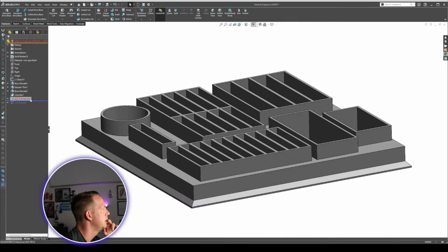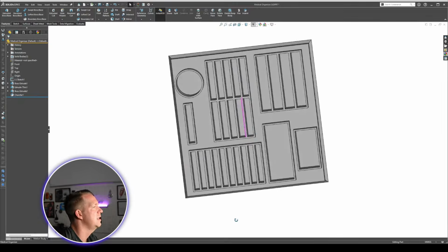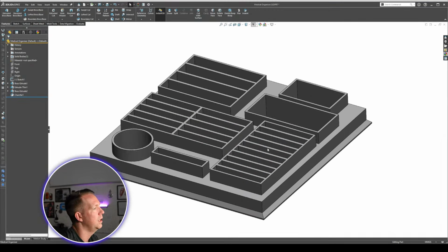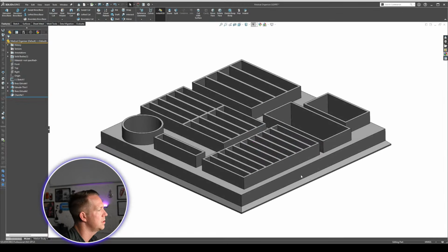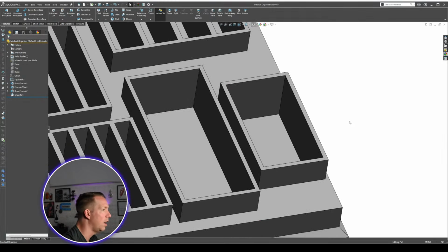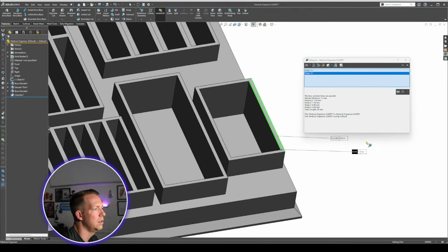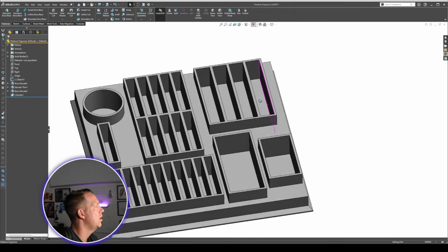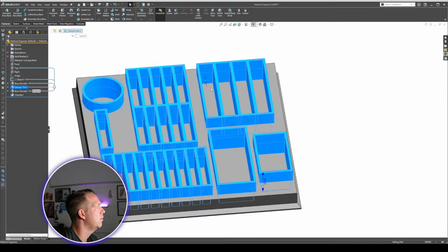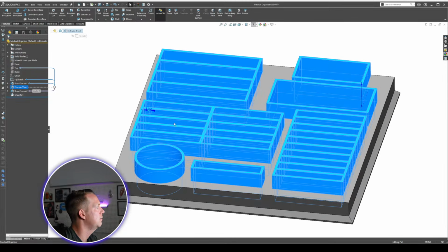Chamfer. Cut. I don't need those. Is this our way of doing it? I think if we did this, I could keep all the external boxes pretty simple and then add some nice radiuses, etc. to everything on the outside. I'm pretty certain that this thickness, 1.5 millimeters, would be quite fine everywhere, suitable, strong enough. I'm not going to have any issues with that. If I want to change it, I can just select this feature here and just change the thickness.